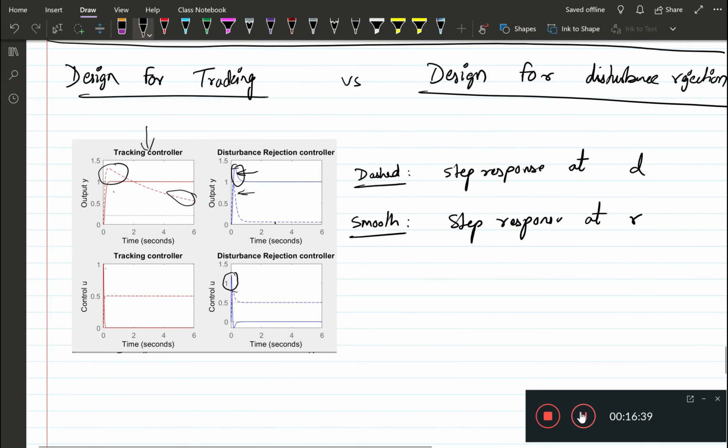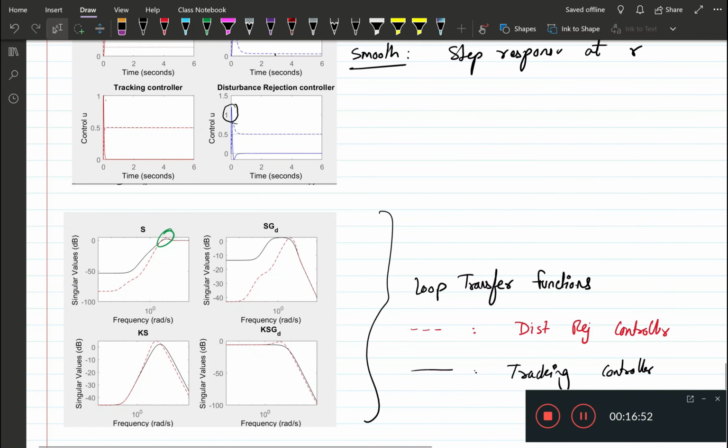Now let's look at the closed loop sensitivity plots and control sensitivity plots with these two controllers. So here you see now the 4 blocks that we designed, or that we tried to shape with the 4 tuning knobs: Ws, Wk, Vr and Vd.